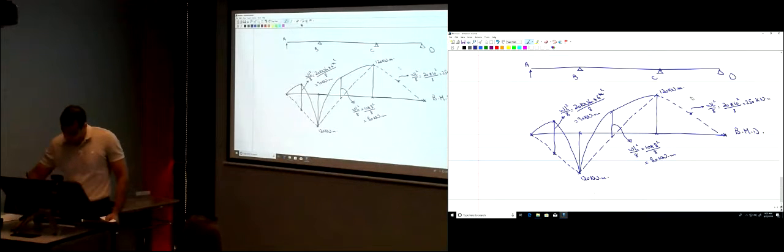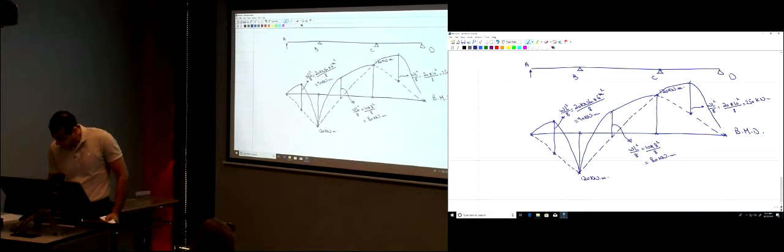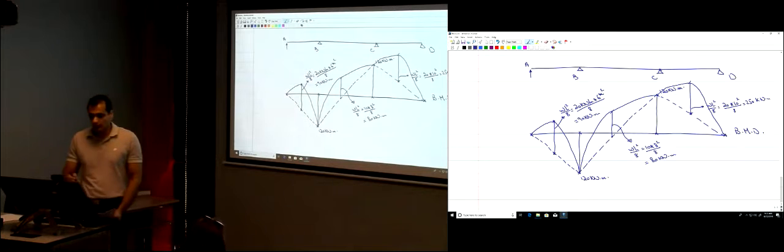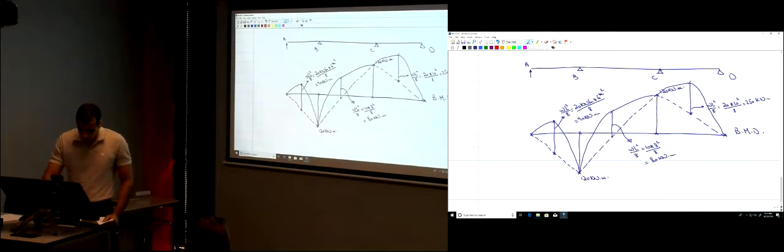That means it's a larger height like this. And then you go your parabola. So this is the bending moment diagram. You need the hatching. So actually this is the bending moment diagram from the solid curve to the line.